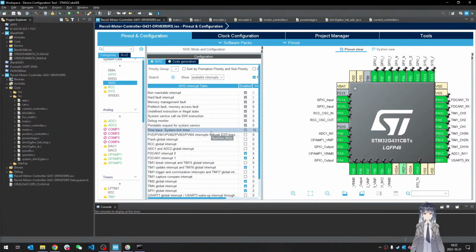Well, the other way to solve this is you can raise the SysTick handler priority, but then you are risking getting interrupted inside your ISR multiple times to update the SysTick, and your entire ISR will be slower, and that's bad. So because of all these, we cannot use the polling method, so we need to use interrupt, and by the way, it's good anyway.